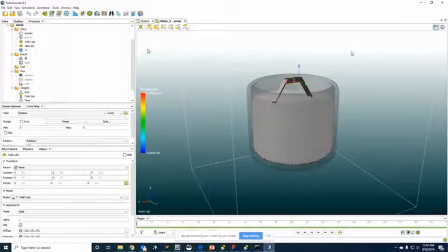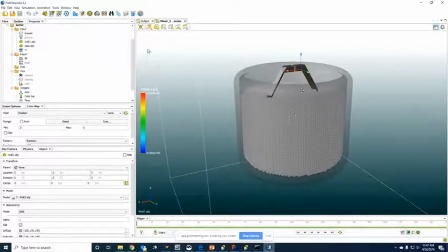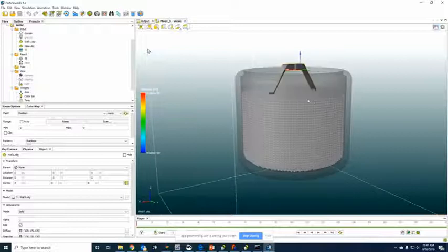Yes. Okay. So now I have this body in here that was imported, and this simulation. At this point is when you set all of your fluid properties. You define interactions between the fluid and the walls, what type of viscosity you have in the fluid, and you'd also define some simulation parameters.